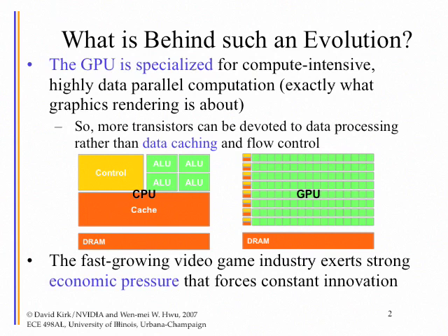Out of random distribution, you will see some of the threads accessing memory, and some of them will come back with data, and the others will still be queued up in the memory access interface, right? So as soon as you have some of them come back, you execute them in the function units, right? And that's how you tolerate memory latency. And that's why you need to have thousands and thousands of threads in this chip to keep it busy.